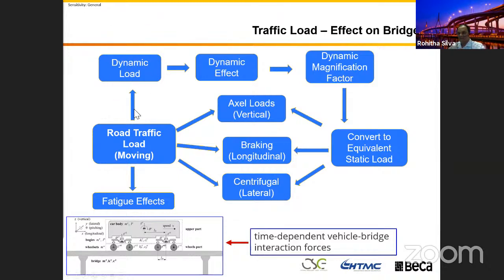And this dynamic effect, because the bridge moving load is a dynamic load, but in the bridge design we don't use the dynamic analysis, we use static analysis. Then there should be a way to convert this moving effect into a static effect, using a dynamic magnification factor. You will see in some codes, Eurocode for example, they included the dynamic effect inside their live load models.